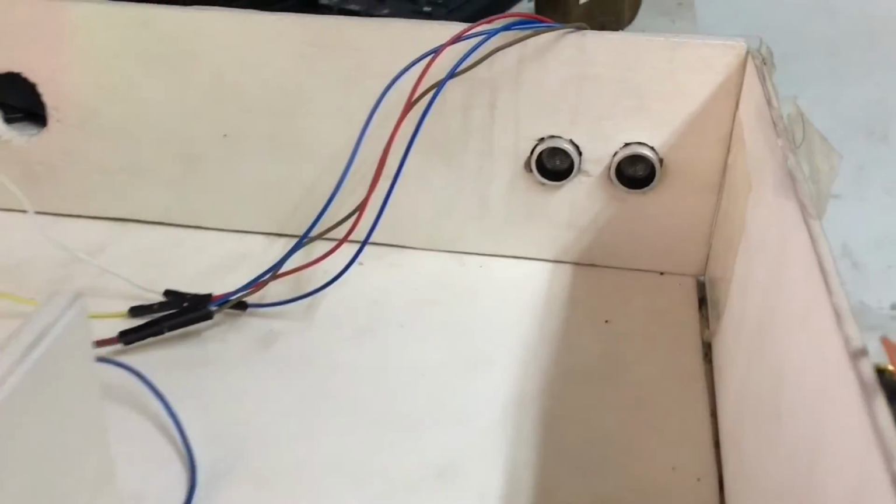First up, we have a laser pointing at an LDR followed by a sonar. These two components are going to help us determine when a person leaves or enters the room. You could argue, why not just use one of these components, since either could be used as methods of detection? Well, the answer is we simply wouldn't be able to differentiate an entry from an exit, and it is imperative that we are able to do so.